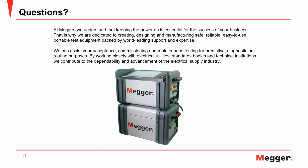And the reason why a change in capacitance is serious is that you have compromised the integrity of the insulation geometry. If you look at the formula for capacitance, it's directly related to the area between the plates and the distance between the plates. That's the reason why when the capacitance changes, it's an indication of mechanical change.